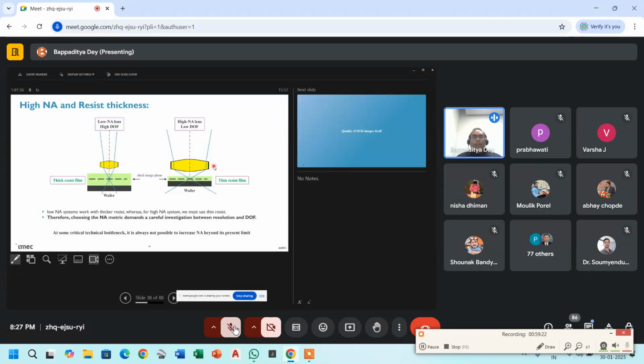Another problem is the thickness of the resist. Why is resist important? Basically, we don't take a blank wafer and print the device directly on the wafer. In between, some of you may already know, we generally coat it with some kind of resist profile. It's a chemical profile. We try to calibrate it in the metrology and defect inspection, and we generally try to follow that.